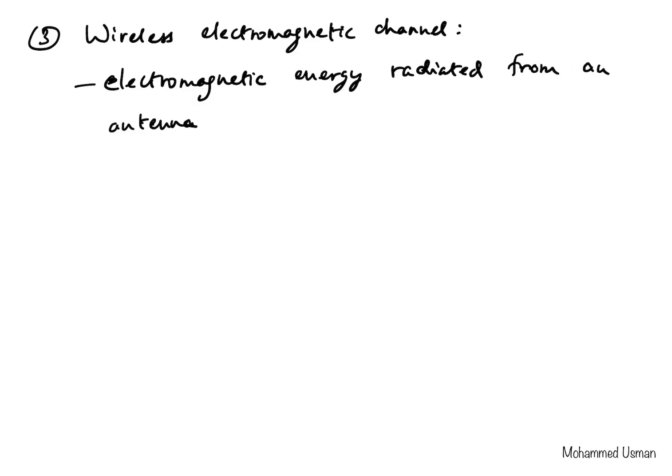So the choice of the frequency that is transmitted on a wireless channel is dictated by the antenna dimensions, because antenna dimension is proportional to the wavelength, and typically, depending on the shape or the type of antenna itself, the antenna dimension is proportional to, in some cases, 1/4 of the wavelength, or in some cases half the wavelength, or in some cases even 1/10 of the wavelength.